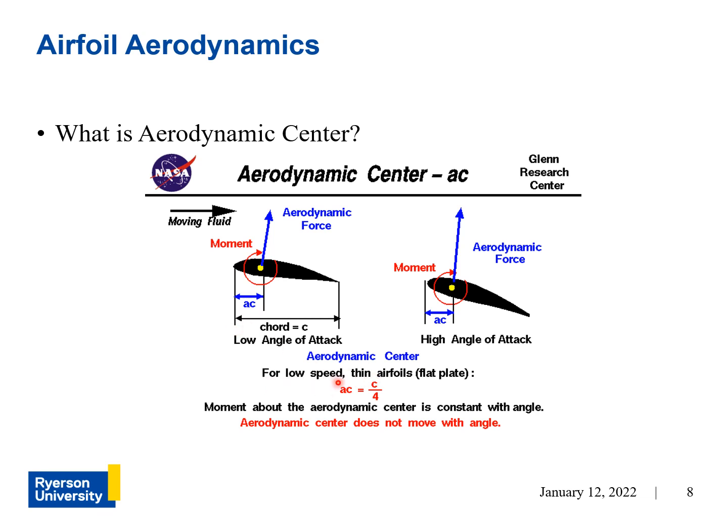Now, the aerodynamic center is not the same as the center of pressure, and the center of pressure is the location where the vertical forces balance. So try not to confuse the two.